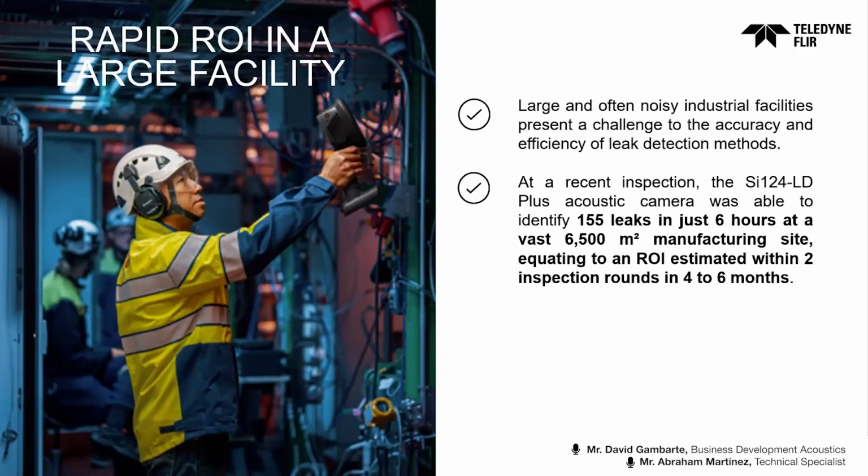Yeah, this is just an example of a return on investment in a large facility. They are normally noisy industrial facilities which present a challenge to the accuracy and efficiency of leak detection methods. There are so many leak detection methods in the market. As an example, in a recent inspection with the SI 124LD Plus, which is the previous model that we still have in the market, and it's a pretty workable model for leak detection, we were able to identify 155 leaks in just 6 hours.